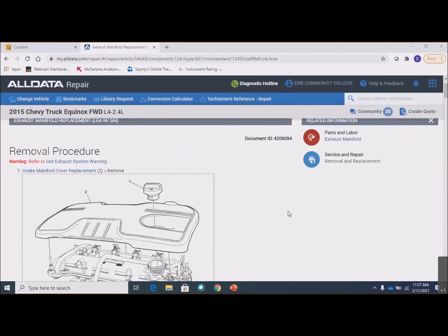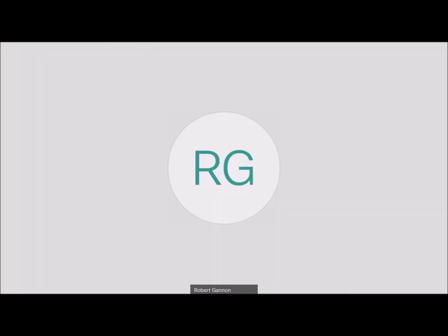So similar now, right? Similar to that story with the Jetta, where it was blaming the engine coolant temperature sensor. So the diagnostic trouble code points you at a sensor, points you at an electronic issue. It was really a mechanical issue, being the thermostat.